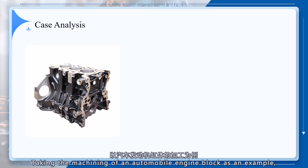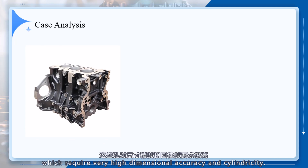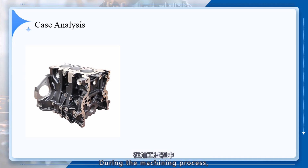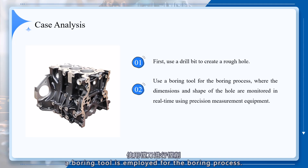Case study. Taking the machining of an automobile engine block as an example, the engine block contains multiple cylinder bores, which require very high dimensional accuracy and cylindricity. During the machining process, a drill is first used to create an initial hole. Then, a boring tool is employed for the boring process.